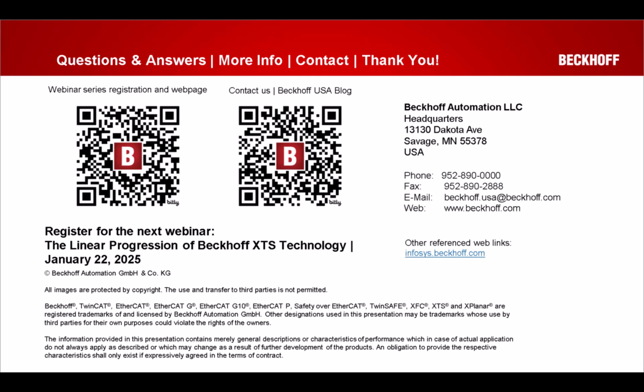And lastly, what tools for post-processing the measurement data does Beckhoff have? Are there any centric around predictive maintenance? Yes, the toolbox that I had alluded to earlier not only lives as, we'll say, more of a visual implementation in TwinCAT Analytics, but also as a PLC library, and that would include tools again like sliding DFT, real FFT, spectrum analysis, cepstrum, all the standard tools.